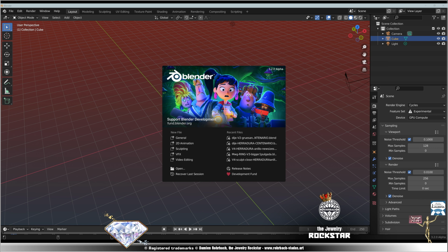And let's go to edit mode. So this face, we're going to move it this side. Let's do an F. Let's do an extrusion. Bigger is better. Mesh normals outside. Exit edit mode. Let's see. Okay, so we are going to use the shrink wrap modifier mostly. Just telling you, because we're going to start modeling the ring.